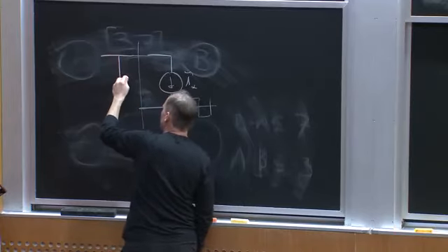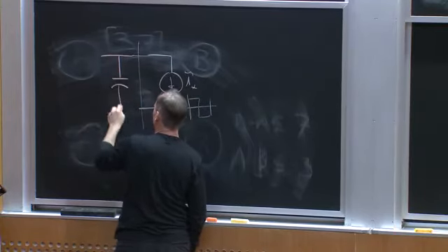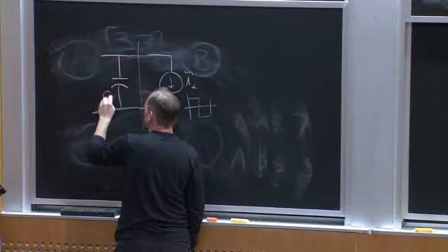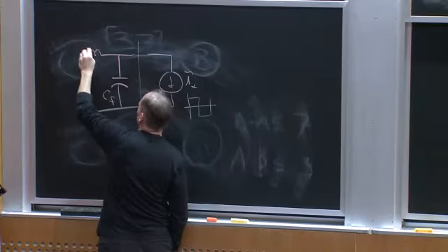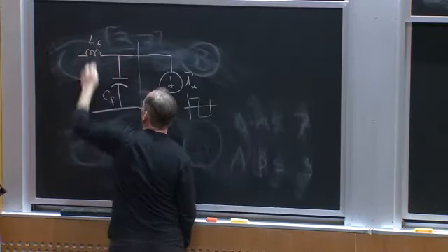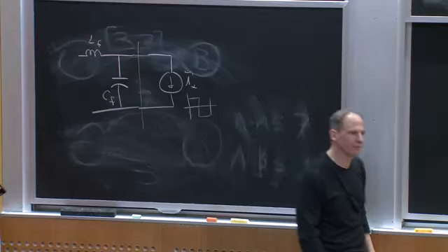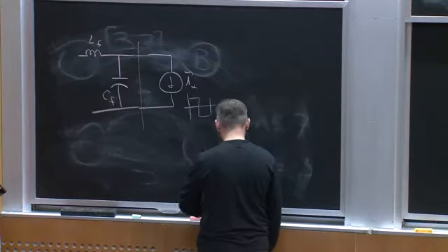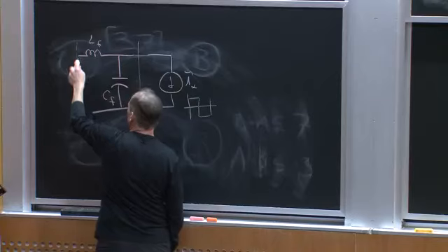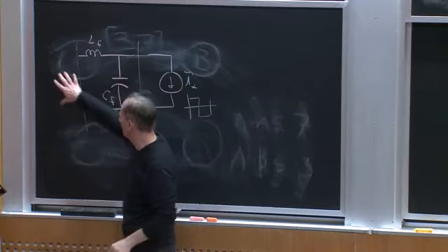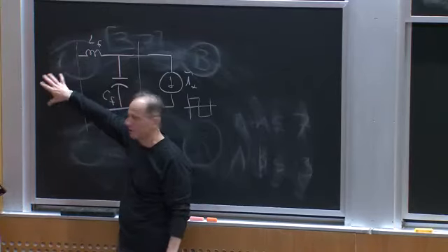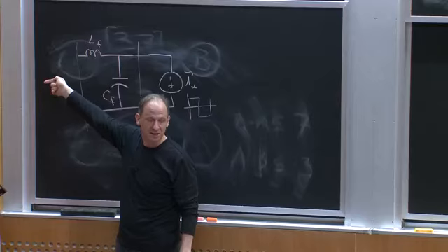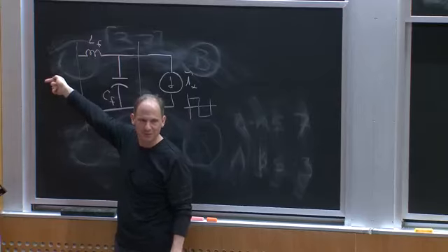Here maybe I would think of having some filter capacitor C_F and some filter inductance L_F as a basic building block for a filter, right? And the notion is I can look back, and on the other side of this filter, depending on whether I'm in my test stand, I'm going to look back into something that looks like Z_LISN, which at high frequencies might be 50 ohms, and at lower frequencies is something else.